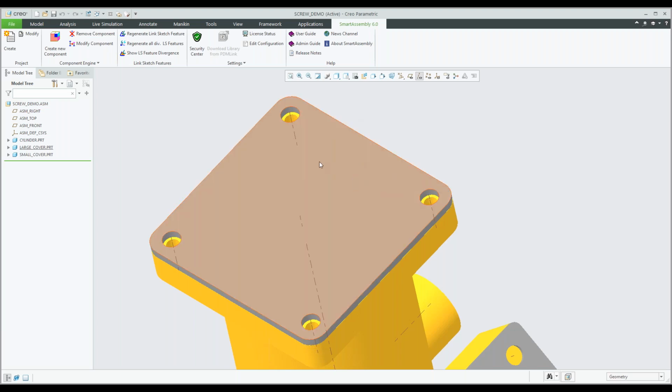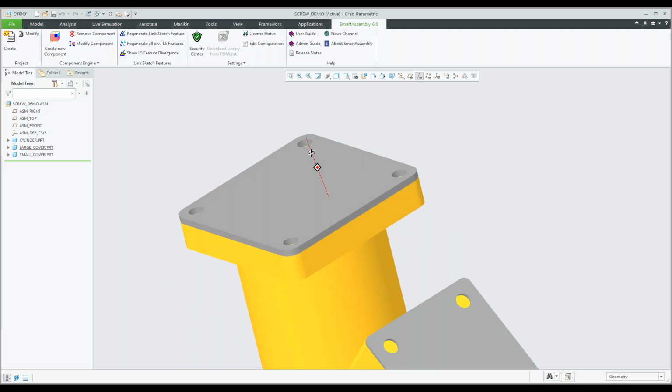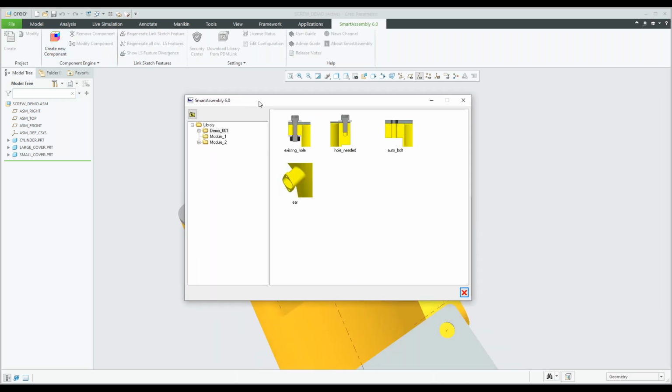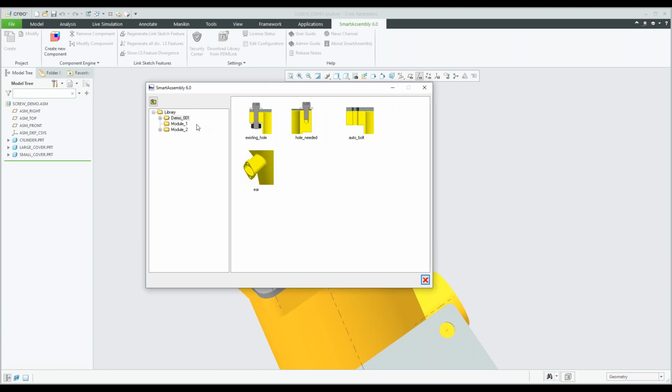And let's say I'm going to add a bolt in here, and I'm just going to go into my section and I'm going to go into my library. So I'm only going to use 3 folders in here now, but there's no limit on these little programs that you can use. So I've got 4 in this folder where I'm going to assign a bolt to an existing hole.